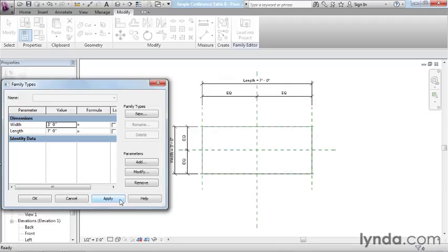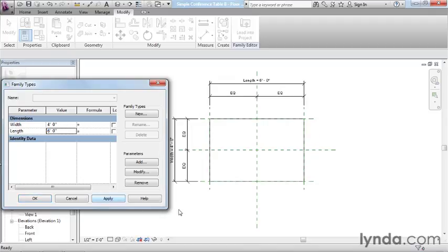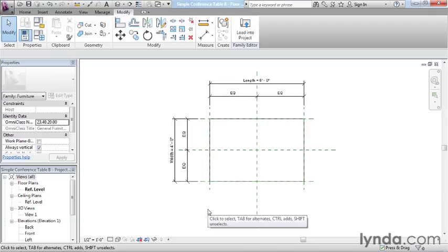We did not click the little padlock icons, and the sketch, therefore, was not locked to the reference planes. But yet somehow, Revit is assuming that we want that behavior anyway. Why is it doing that? Where is that assumption coming from?